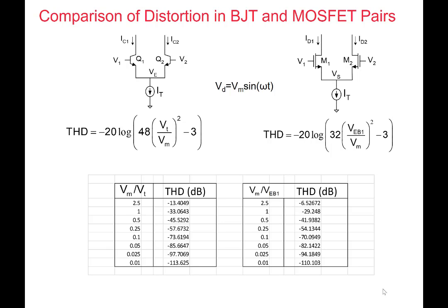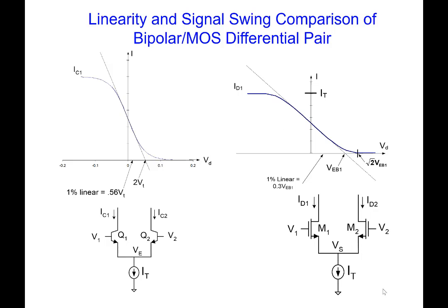Make sense? So if you use the bipolar input stage, which looked highly nonlinear, as the first stage of a high gain amplifier, the amplifier is very linear because your signals are so small. It might get worse when we get to higher frequencies because the gain rolls off, so we don't keep that gain of 100,000 at higher frequencies.